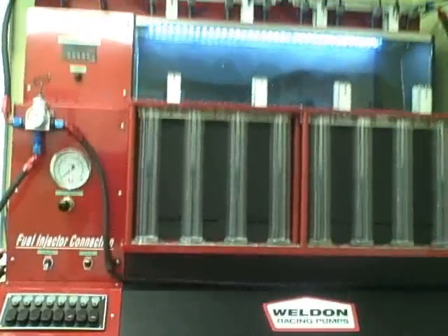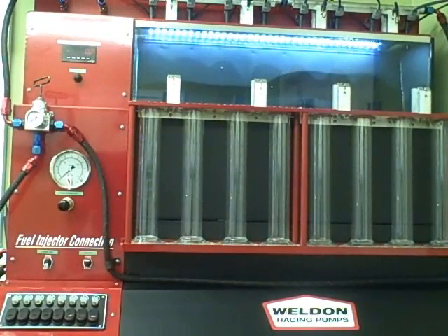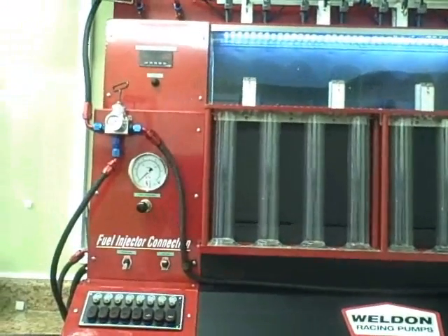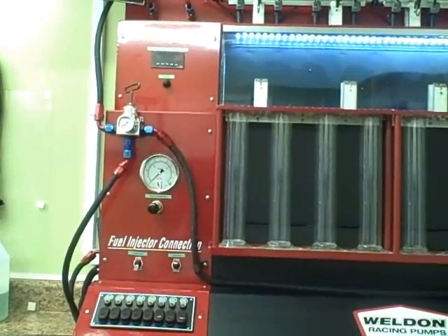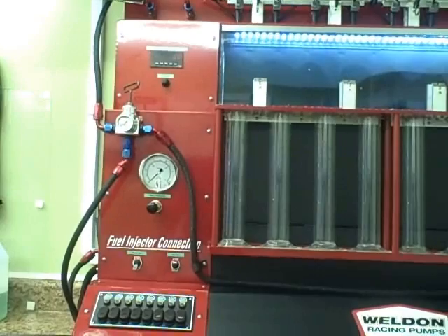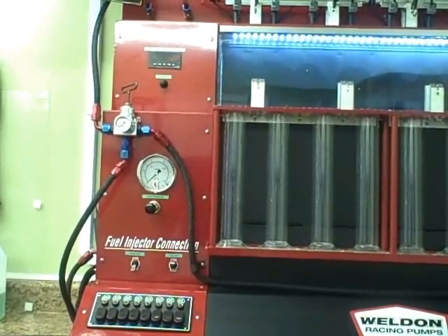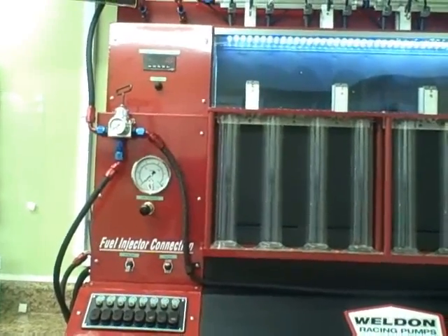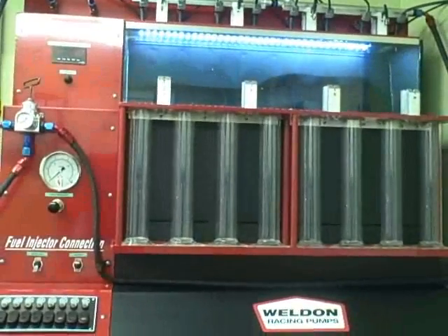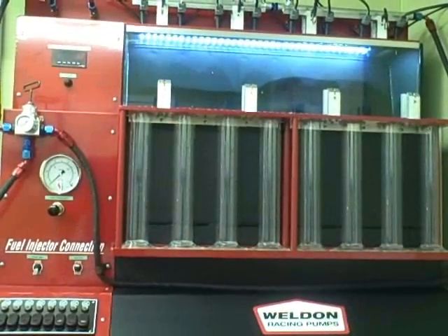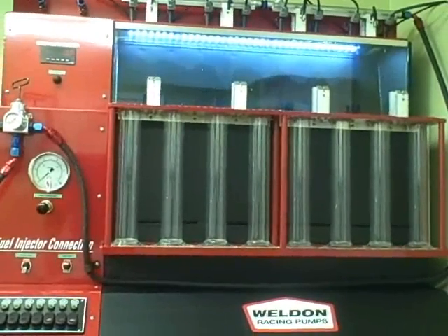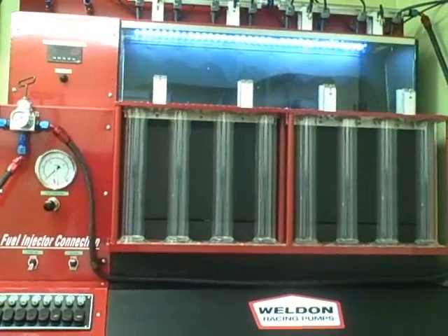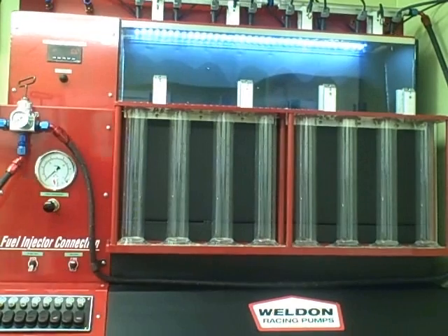So I'm going to go over here and get this thing fired up. By the way, the gauges, one is pre-rail, the other one is aft rail, and they both have to be the same. We're going to run this test at 4 bar. The injectors that are on the machine are modified Siemens 60s that we made flow 76 pounds at 3 bars. So let me get this thing fired up and you can see how it works.